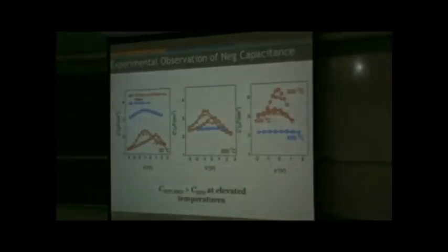And these are grown using this pulsed laser deposition technique. Now these are some experimental data at room temperature. What we are comparing is strontium titanate dielectric material, 48 nanometer, with strontium titanate and PZT. So it is still 48 nanometer, but plus 28 nanometer extra thickness sitting on top of it. At room temperature, I find a hysteretic behavior of the heterostructure.